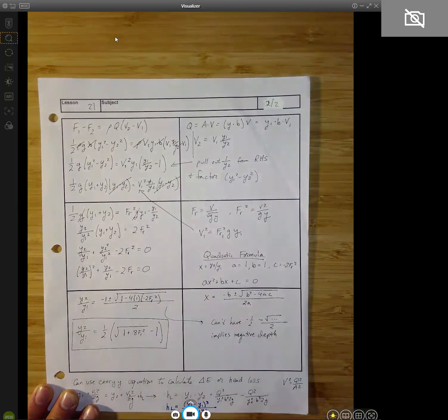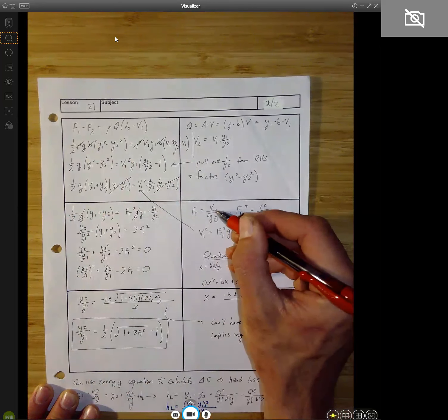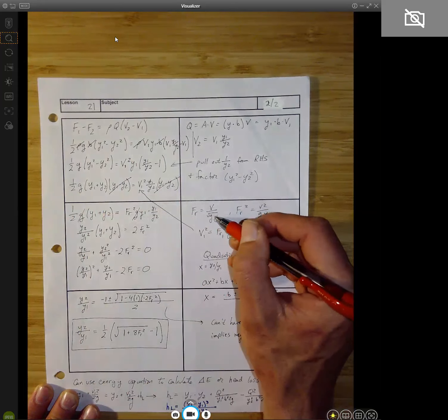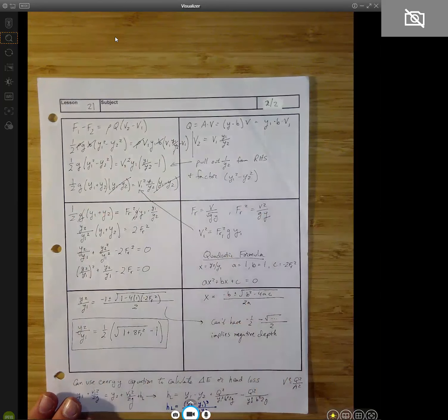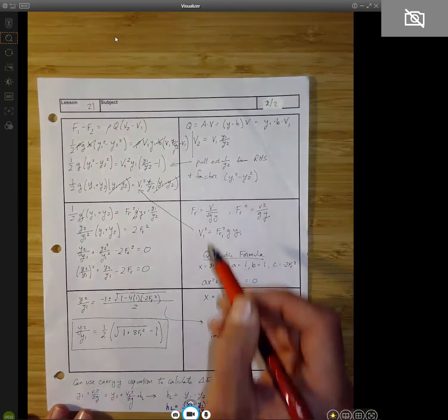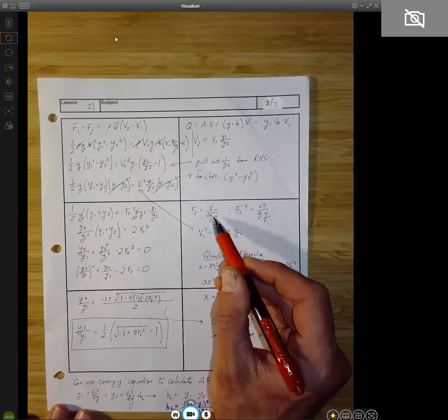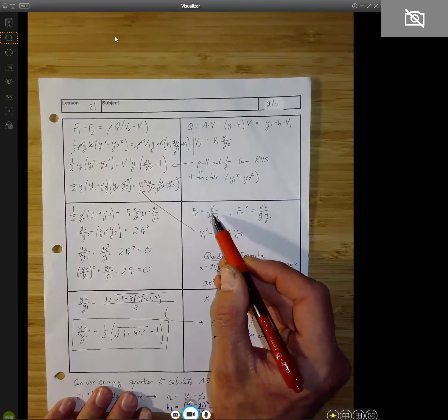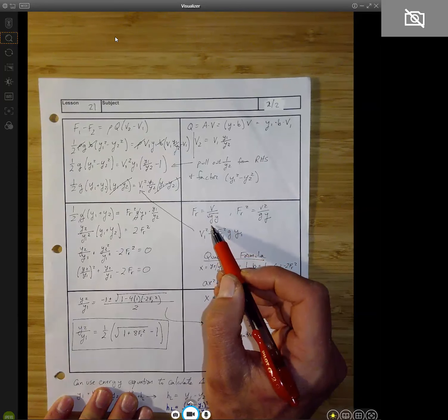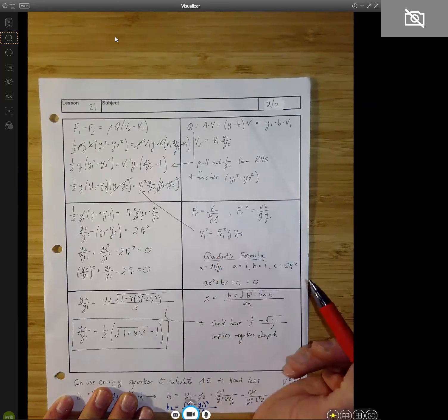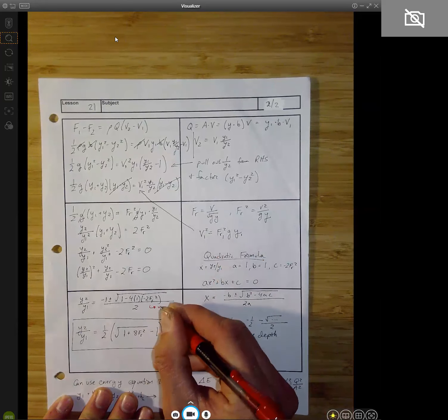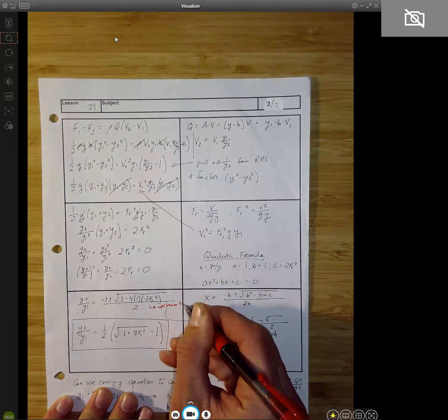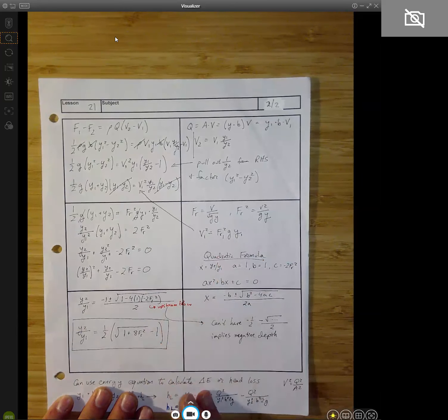And if you recall, the Froude number is equal to the velocity of the flow divided by the square root of gravity times depth. So that's Froude number. It is going to be greater than 1 in the upstream direction at the supercritical flow, right? So Froude number is equal to 1 at critical flow. It's going to be greater than 1 for supercritical flow, and it's going to be less than 1 for subcritical flow. So this Froude number is going to be the Froude number for the upstream flow. And if we know the velocity and the depth, we can calculate that Froude number.